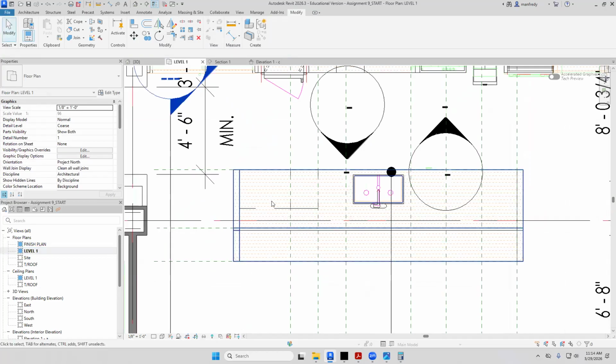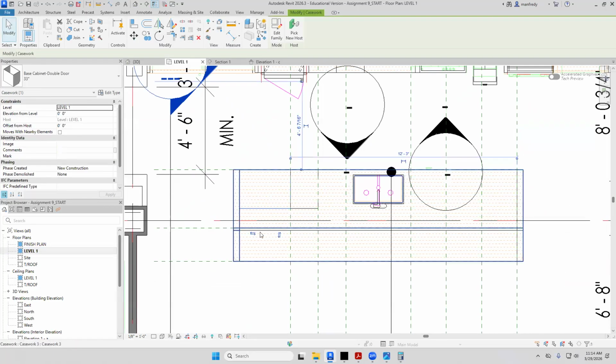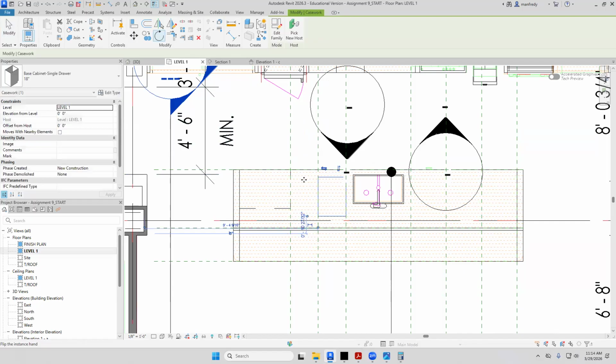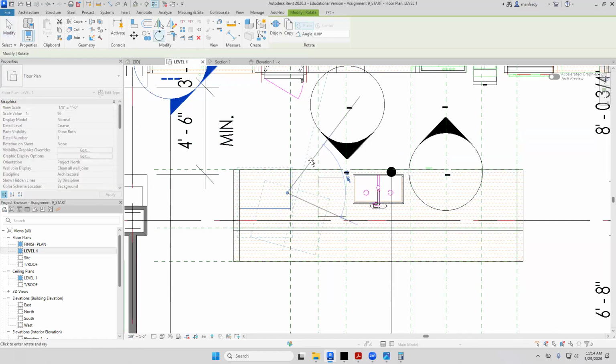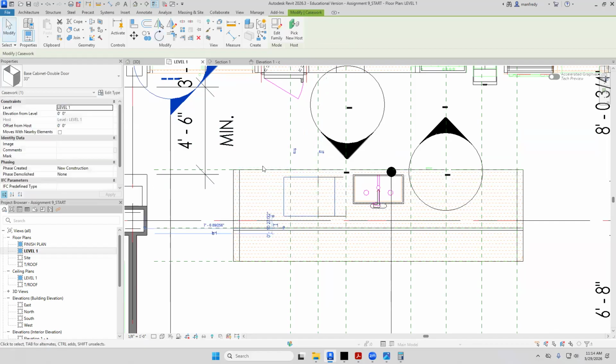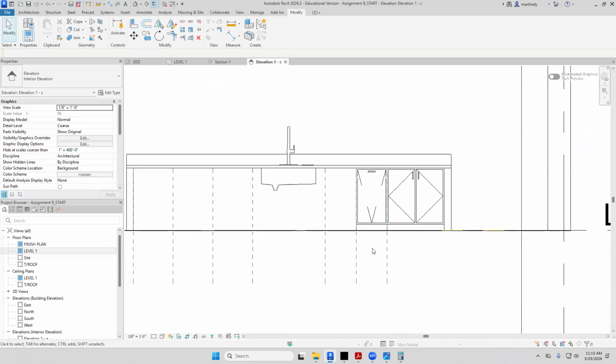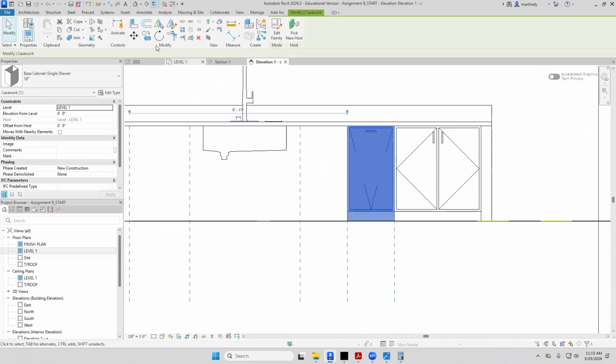And these are backwards. The arrows are facing the front of the cabinets. See the arrows here? Arrows here? That will be the front. So these are rotated 180 degrees. 180, then here the same. That's how you know when they're facing the right direction. 180 degrees. And then I can just put them back against that wall, against this countertop. Against this, I can use reference planes now and just line them up. Okay, there they are.